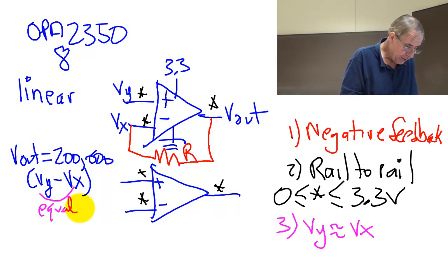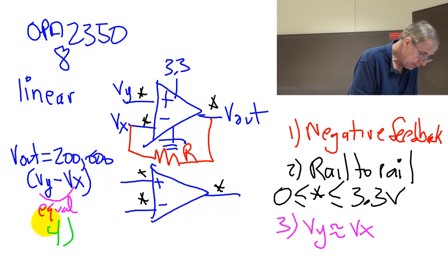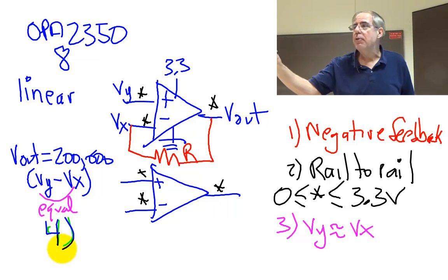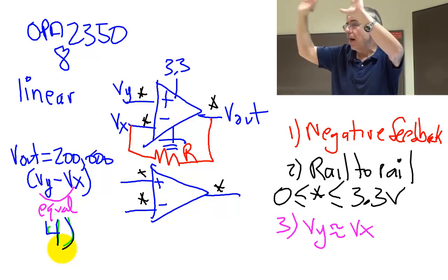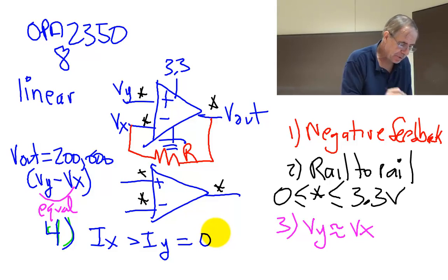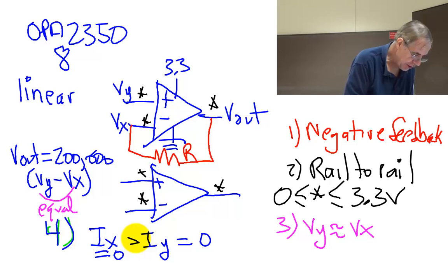How about we do next rule number 4 in green. Can you see the green? Now let's make rule number 4 in blue. And that is, from an ideal standpoint, from a computer scientist's thought about op amps, the current into the two terminals is going to be approximately equal. Not equal to each other, but they're both going to be equal to 0. So that's rule number 4.